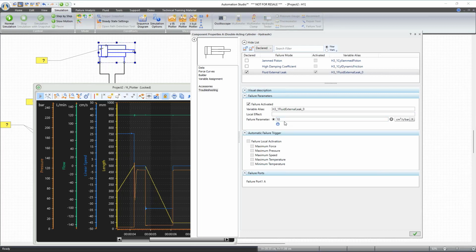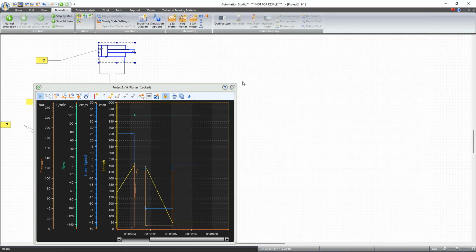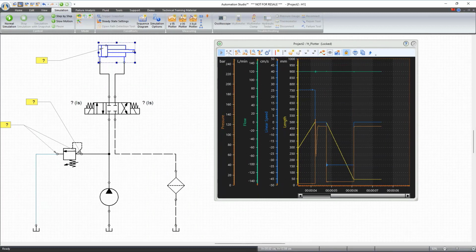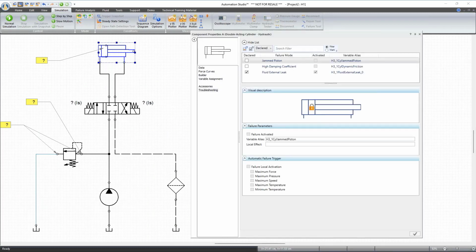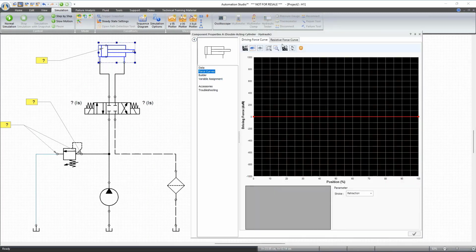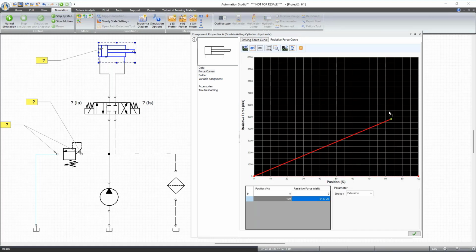This will be really convenient to see, since there is always leakage in hydraulics, what is the maximum acceptable leakage to make sure that the circuit meets the desired performances. Okay, in my case, I will just put that failure in, and as I run the simulation back, once again, if you want this failure to be effective, we'll need to have some load, make the pressure rise. Okay,